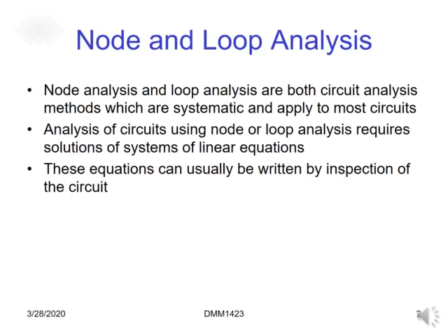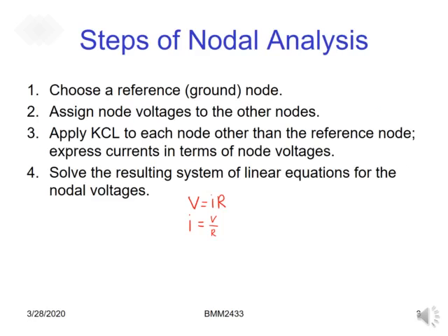For nodal analysis, we are going to analyze the circuit using nodes, and the nodes require a solution of a system of linear equations, and these equations can usually be written by inspection of the circuit. These are the steps in order to analyze using nodal analysis.